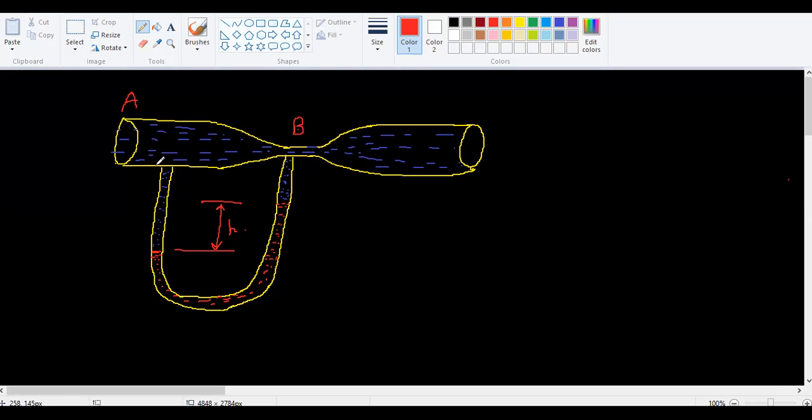Of course, I showed the A here; maybe the tube I can show over here, A and B. So what is the simple principle you have been using? Energy at A should be equal to energy at B. You see the height is the same, which means the potential energy does not change, right? In the derivation, we studied a tube like this, where the height is different. That's why we brought in mgh1, mgh2, and rho gh1, rho gh2 in the Bernoulli equation. Here, since the height is the same, we don't worry about the potential energy.